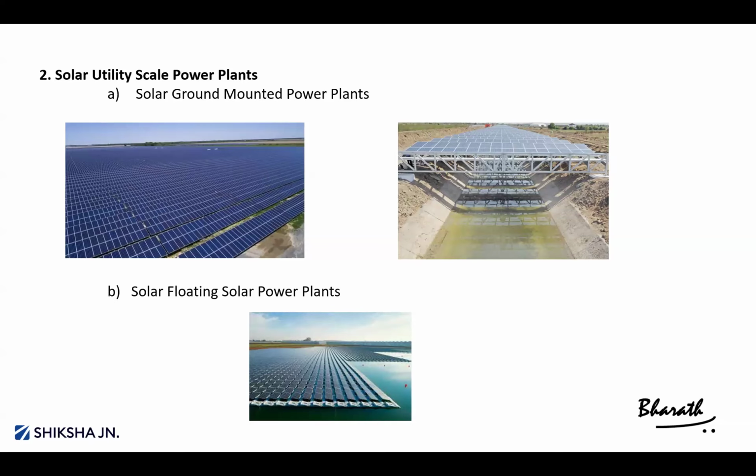Actually, it goes to the grid, and from the grid that industry guy will take it. So discoms will charge per unit, like 50 paisa, for wheeling charges and for infrastructure charges. So ultimately, this industry or shopping mall or any client will benefit because of around 2 rupees lesser price they are getting compared to whatever the grid power.